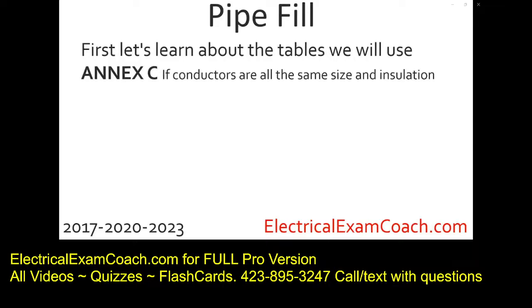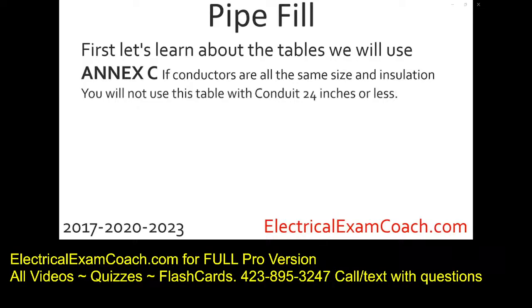And if you've tabbed your code book, you have an Annex C tab. And if you haven't tabbed it, you can just follow along. If the conductors are all of the same size and insulation type, we get to use like a cheat sheet in Annex C. It's one of my favorite tables in the code book. You will not use this table if the conduit is 24 inches or less. Now, the code book uses the term nipples, but I want you to imagine in your mind, anytime the conduit is 24 inches or less, you're not going to use Annex C. You're going to use the method that I'll teach you in Lesson 7.2.